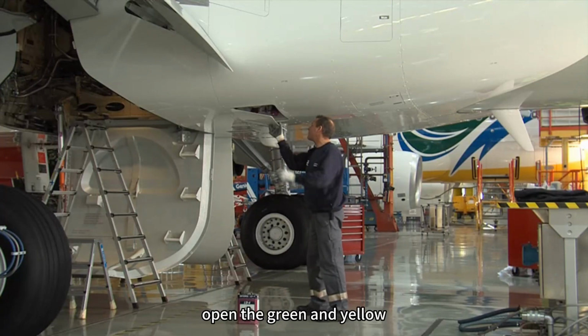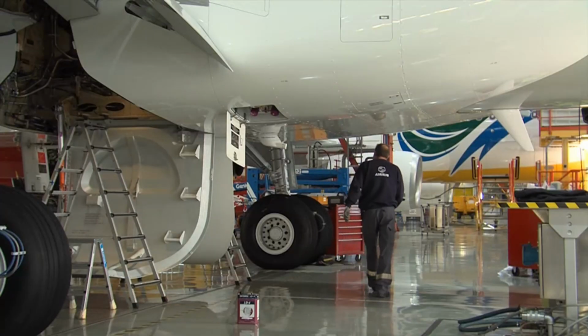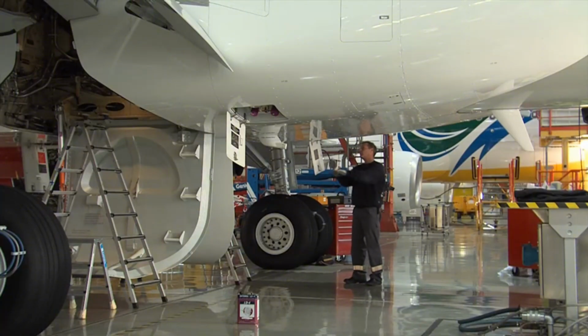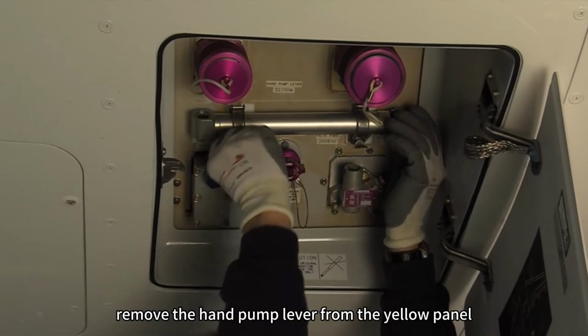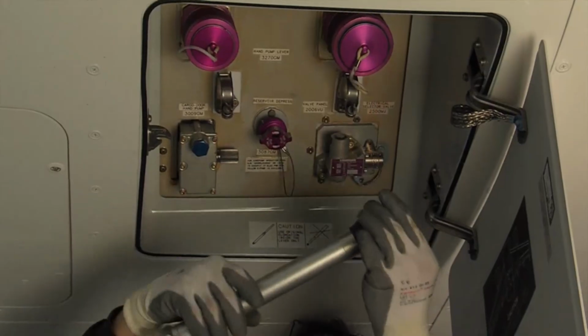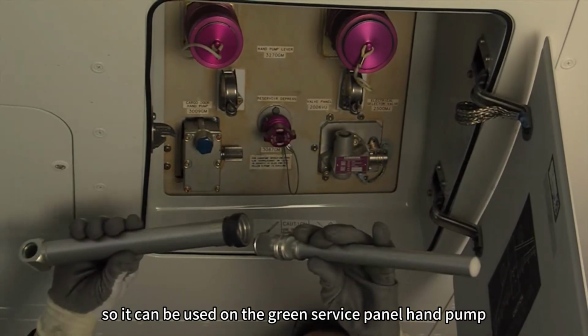Open the green and yellow hydraulic ground service panel. Remove the hand pump lever from the yellow panel and assemble it so it can be used on the green service panel hand pump.